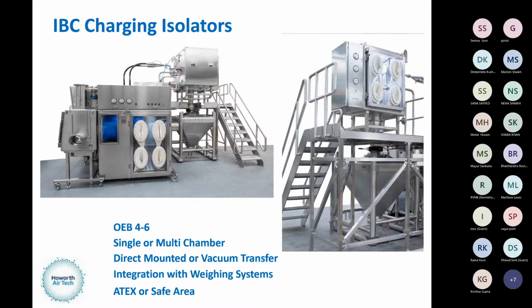So this particular example shows vacuum transfer systems from the isolator into the IBC. What you can't see on that image is there's a downflow booth where we're charging the excipients exactly the same way. You can just about see on the top left 2 black hoses. One of those hoses goes to the isolator, one of those hoses goes to the booth. So we can transfer the materials basically with a recipe into that IBC. That IBC then goes away to be blended and then carries on as part of the tableting process.